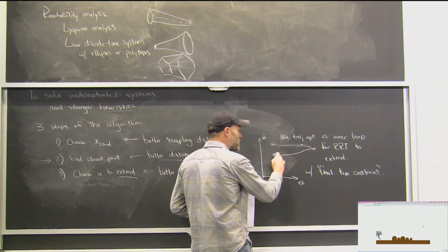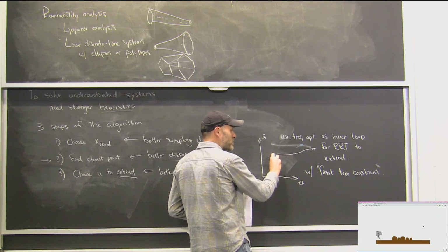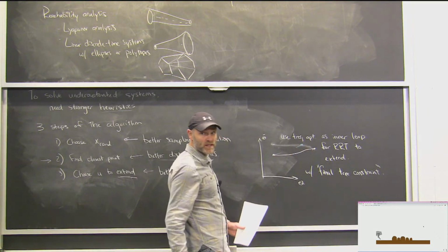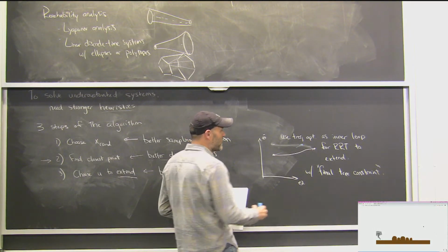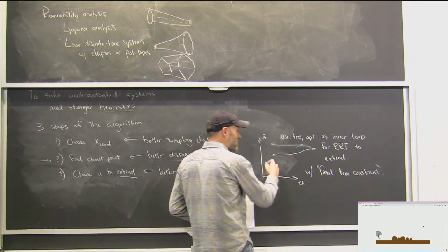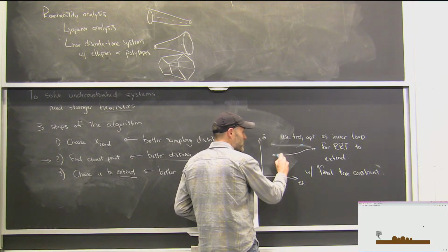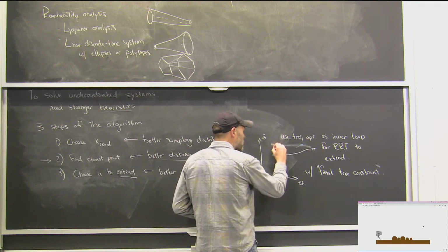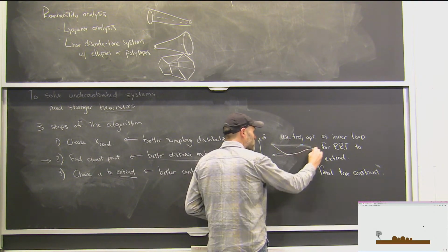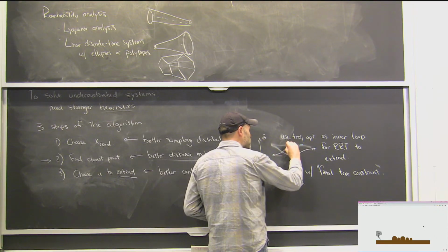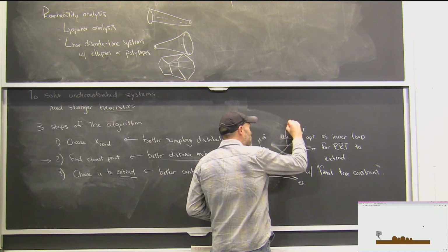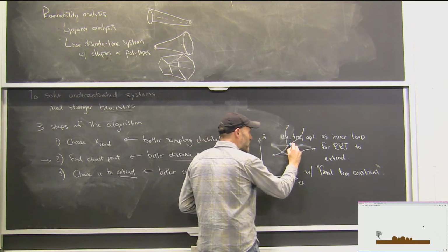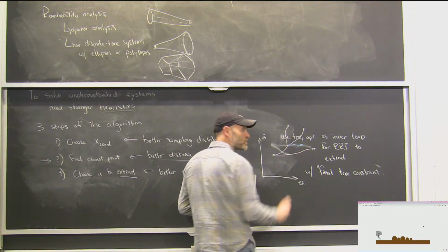I find it much more effective in trajectory optimization to, instead of constraining to go exactly from this point to exactly this point, which is a hard two-point boundary value problem, use the flexibility in trajectory optimization to say my initial condition could be anywhere along the existing tree. So if I have a whole dense network of possible solutions in an existing tree, rather than saying this was the closest point, only grow from here, allow my trajectory to connect up anywhere along the continuous existing paths in the tree.